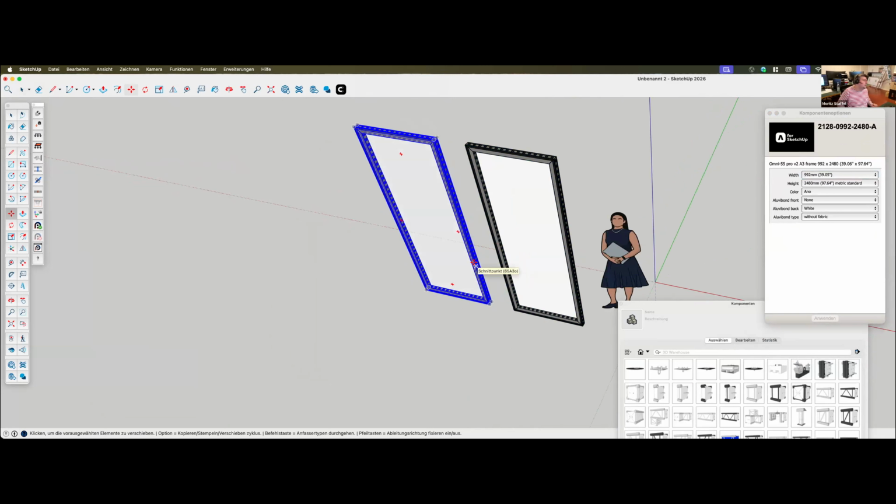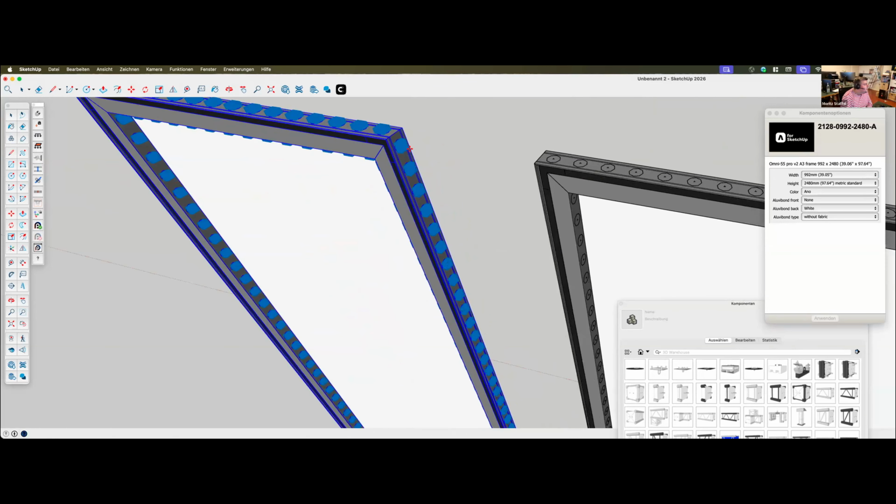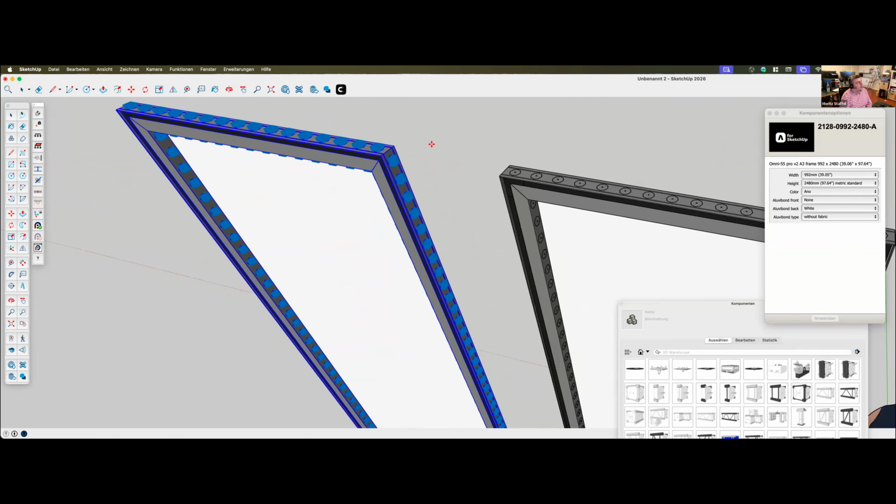A really important thing for Production Assist, so that you actually can calculate, is that you're using the snapping functionality from AluVision. The different frame parts really need to align. So if I have these two things, I can use the snapping functionality, use grab points to connect parts, click on it, and then I got these blue bubbles. These blue bubbles allow you to select which other bubbles you want to align to.